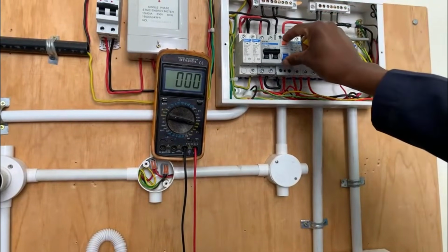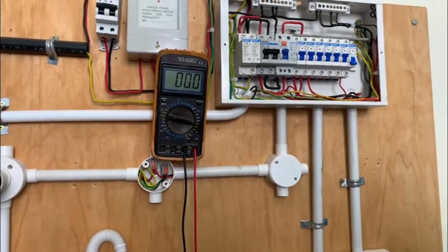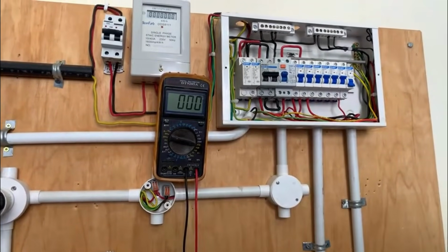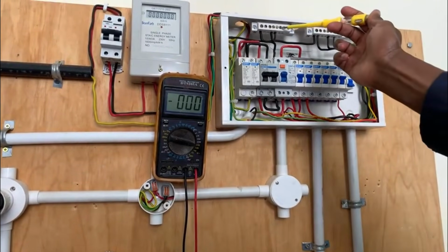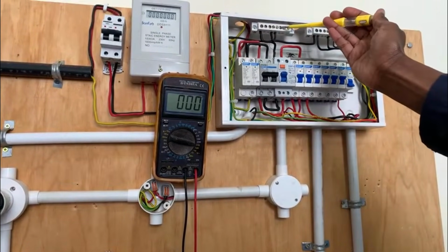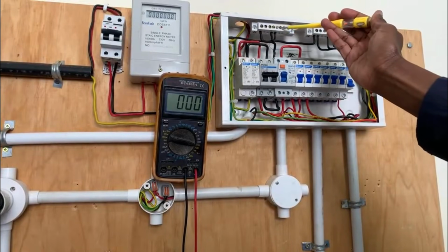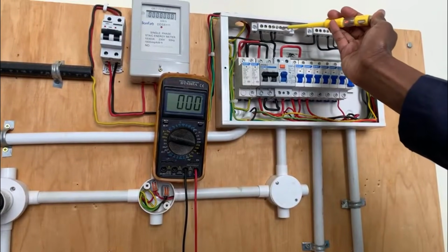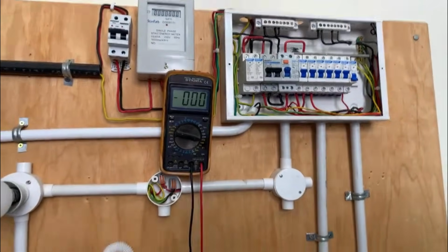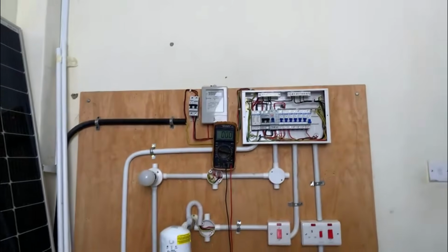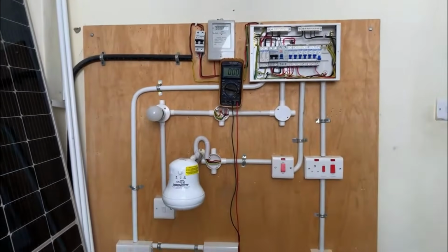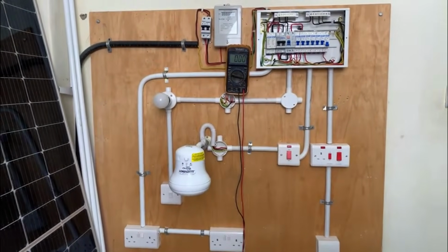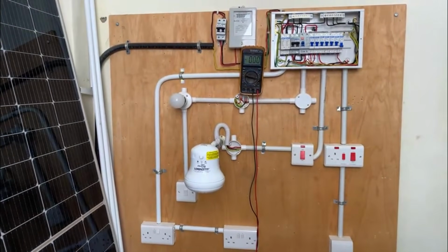So now we switch it on. When we switch it on, we have activated the neutral. When we place our tester right there, it's lighting. Can we say lighting or turning on, or what is the correct language right there? Look at that. There's a problem. There's a huge problem. Why is the neutral having current flowing through it? What could be the fault that is right there?